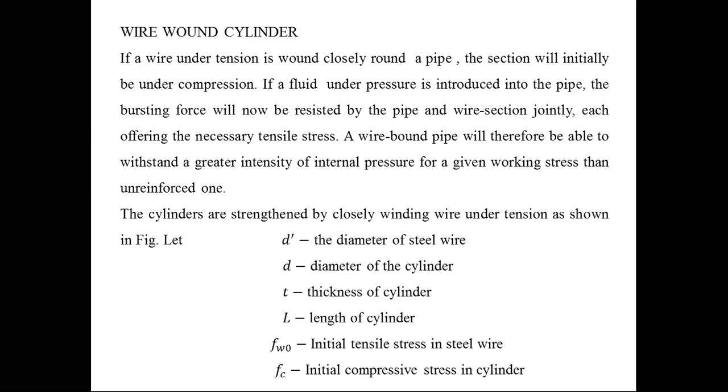That is the important point. Here in the wire wound problem, the compressive nature comes from a thin steel wire, which is tensile in nature. But that tensile stress in the wire will act as a compressive force on the cylinder when you wind the wire onto the cylinder. So I will mention the tension in the wire. Listen carefully. The tension in the wires gives rise to external pressure on the cylinder, and hence introduces the compressive hoop stress in the cylinder.